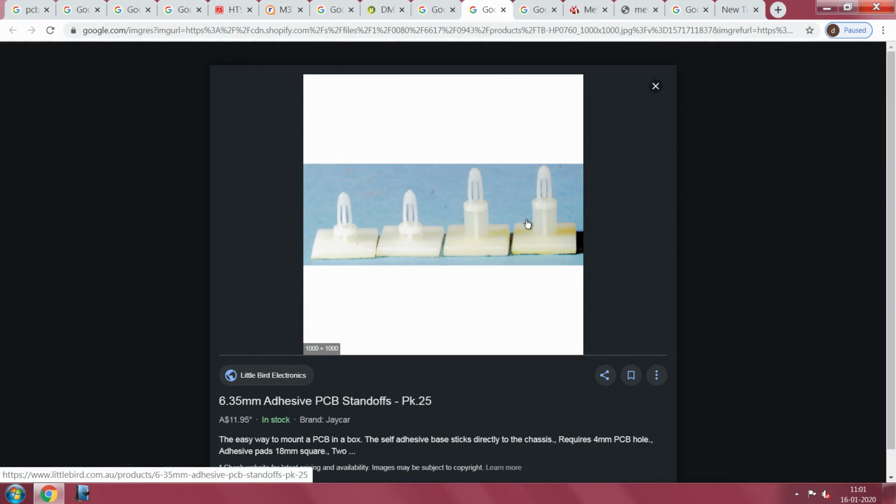Now, one more time, if you have your standard enclosure, you can move these things wherever you want, place it, and you do not even need to have the standard enclosure directly, because you already have a solid model of the enclosure. You punch up the solid model in part of your library, push all these things, see where best you can arrange these things, and that is where the advantage comes for you.